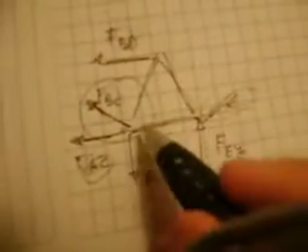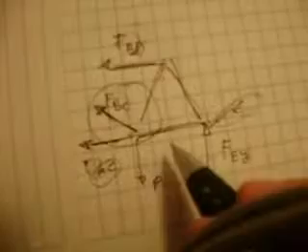So we have this force in the y direction. What will we do? If we make a summation of forces in the x direction, we will have this one and this one, and we won't be able to solve for this one. We cannot use a summation of moments either, because the same thing will happen: we'll have too many unknowns. So what we do is make a summation of forces in the y direction, because we know this force and this force, and we have this force that is the one we're looking for. We just have to get its component in the y direction.